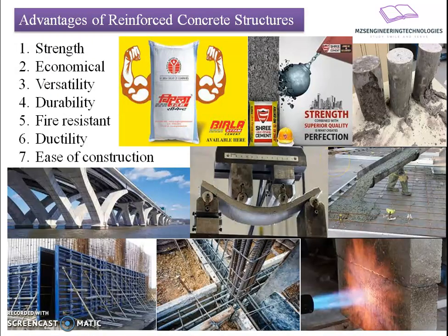Let's go towards understanding the advantages of reinforced concrete structures. The very first one is strength. As I already stated, reinforcing bars when added to the concrete improve the tensile strength capability and also ductility. That's why it makes it a suitable material to carry loads. Similarly, we have seen advancement in the material strength, and the knowledge of the material characteristics has led to the development of high strength concrete and high strength steel. Thereby, the composite prepares a high strength reinforced concrete section.